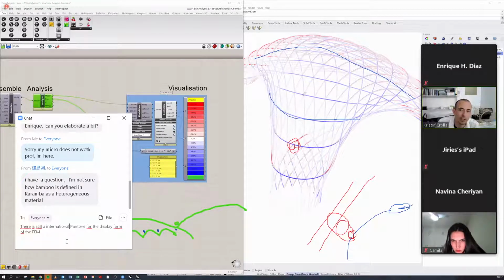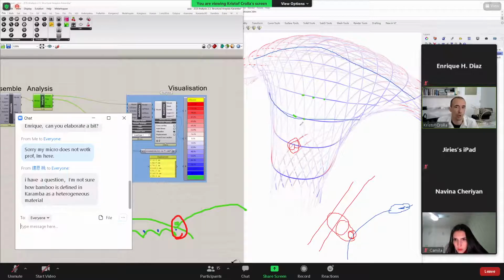If you do it on every intersection point of your structure, then your overall membrane is going to work pretty uniformly as a continuous shell. If you do it only on every fifth one, then you do risk having load concentrations in the points that are associated just with where the metal wire is going through. And those load concentrations can over time become points of weakness. But that's a balancing act that you would have to do with engineers with proper analysis tools, I would guess. If you're doing it more intuitively, then I would just make sure that you don't make it too sparse, because without the diagonals there, the structure is much more wobbly.